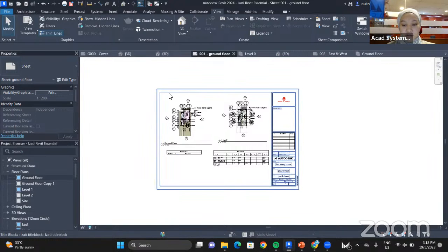The most important new feature for Revit 2024 is the Toposolid. Instead of having topography as a topo surface, which is a surface, now topography is solid geometry and called a Toposolid. I'm going to show you how we create the Toposolid.